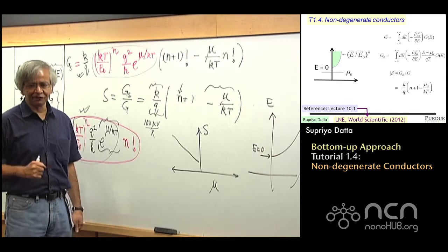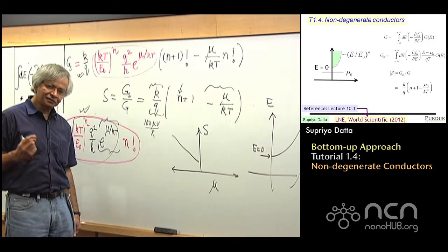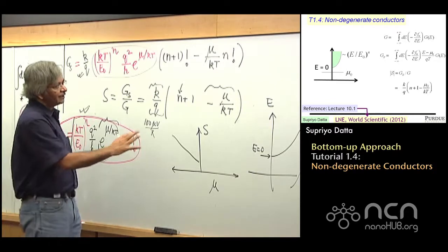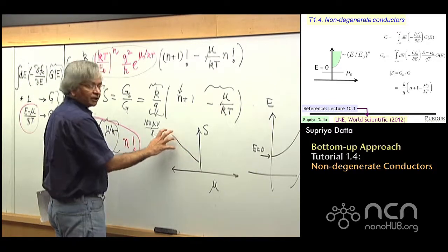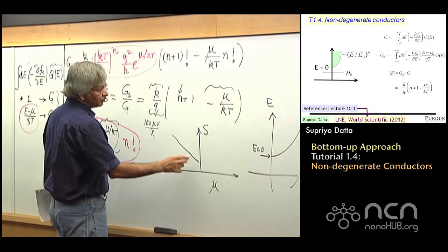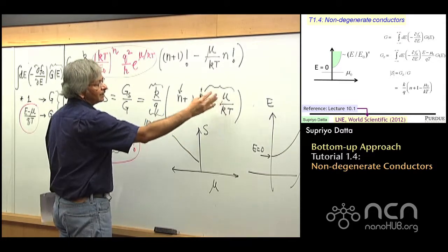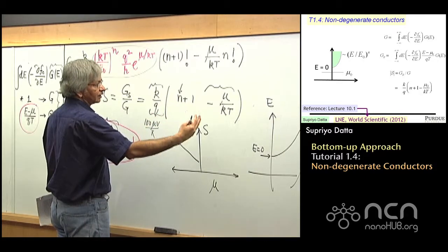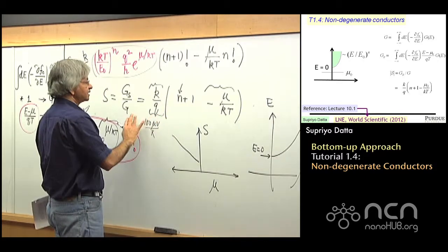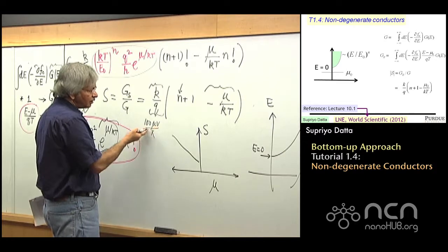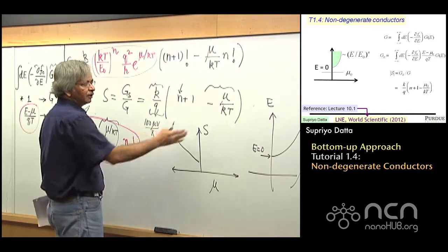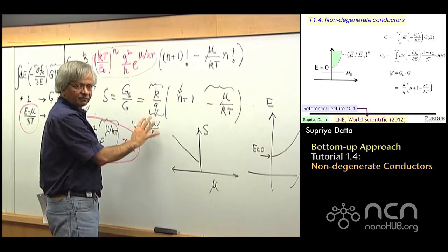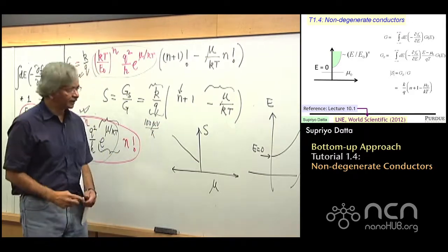As electrical engineers would put it, you've got a voltage source, but you can't draw any current from it. So you really cannot use it ordinarily. You'd like to have mu be a couple of kt or so, which is why with the best semiconductors you usually see a Seebeck coefficient on the order of k over q, where mu is just 1 kt, or maybe twice or thrice this. That's what you would typically get.